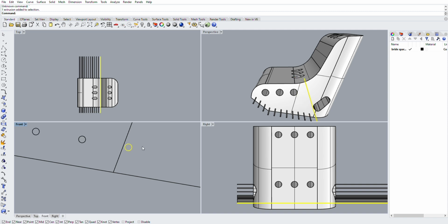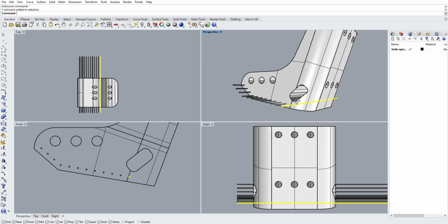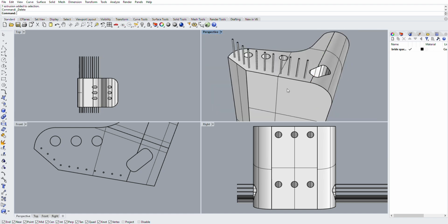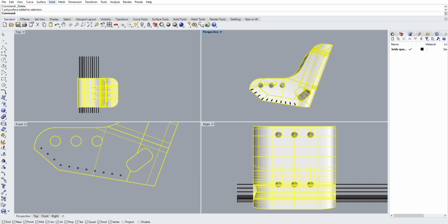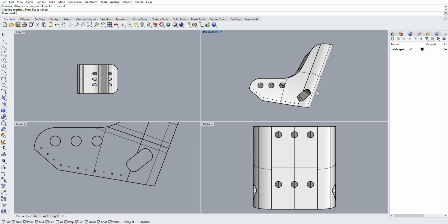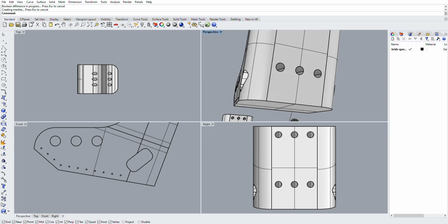Now, I'm building this with straight bends. I'm not flanging on the curve. So the sides and the back will only be attached on the sides and the back. The curved section is just going to float. That area is going to be supported by a different gusset later, which I don't show in the video, but it'll just be a simple bent piece that'll rivet to the bottom and the back to triangulate that back corner. I just don't get to it here because honestly the video ends up pushing it a little bit.